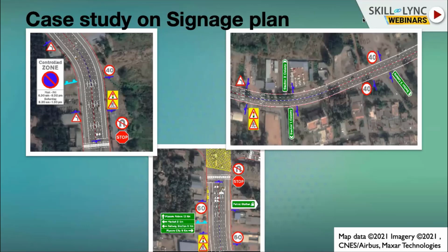It's not always the travel path distance that matters when it comes to the placement of the signs. We'll also need to maintain some lateral clearances. Depending on the size of the signs, larger signs like gantries, which are provided mainly at grade separated junctions, can have a huge lateral clearance.